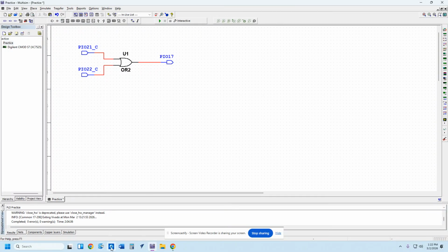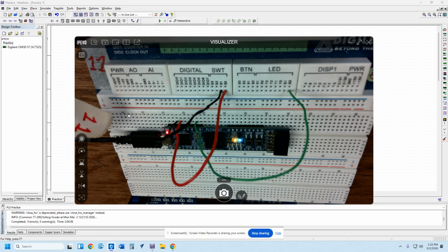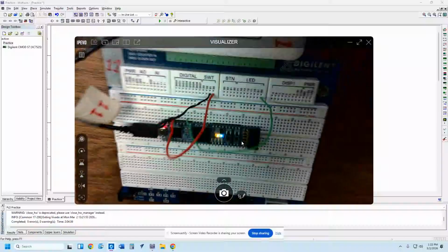When you look at your chip, you're going to see a blue light is now lit. Everybody see the little blue light there? So red power light, yellow ready light, but the blue light indicates that the program is successfully uploaded. So now it's on me as to whether or not this thing actually is wired correctly, because that's the other obstacle that you may face. You may have hooked the wires up wrong, or you might not have hooked them up well, okay?